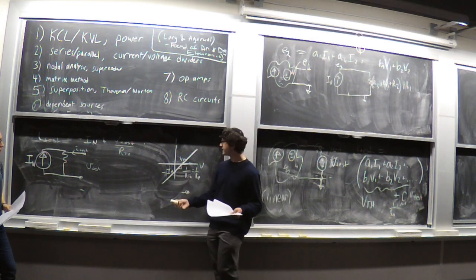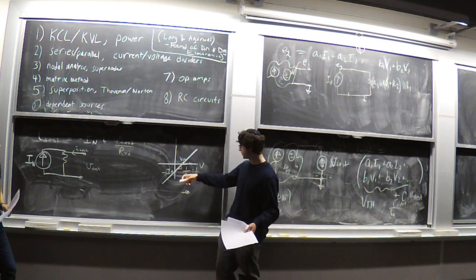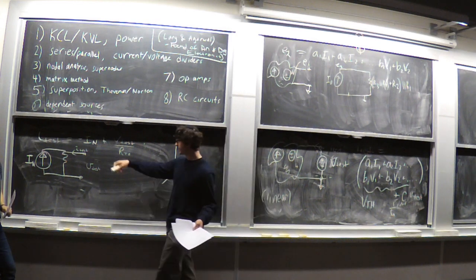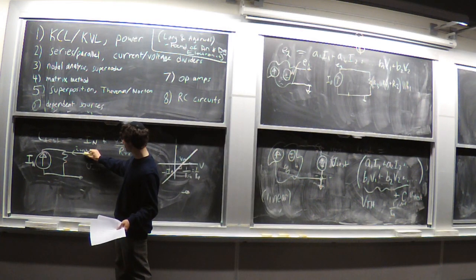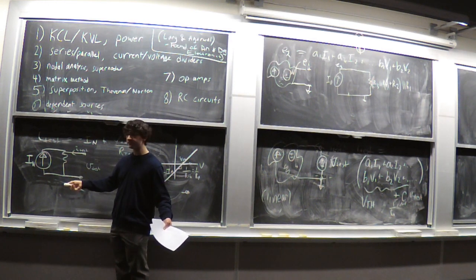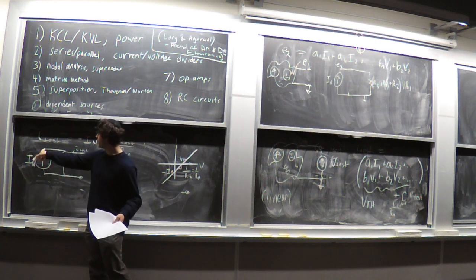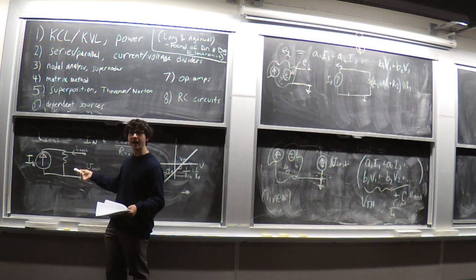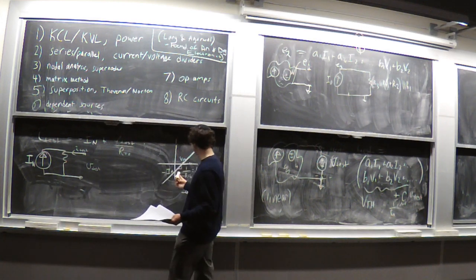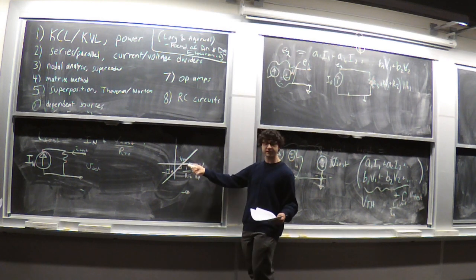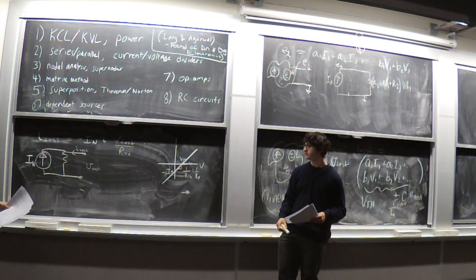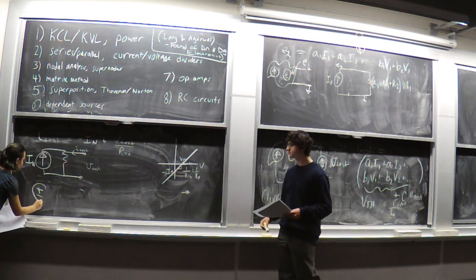And the idea behind that is, right, this is the IV curve. So where we intersect the I-axis is when V equals 0. So if V were to equal 0 here, these would be at the same voltage. There would be no current going through the resistor. And so I test would be facing in the opposite direction of IN, which is why our I test is the negative of the Norton current. But yeah, it's key to remember: you intersect the V axis at the Thevenin voltage, the current axis at the negative of the Norton current. And I'll add this back, sorry for erasing that.